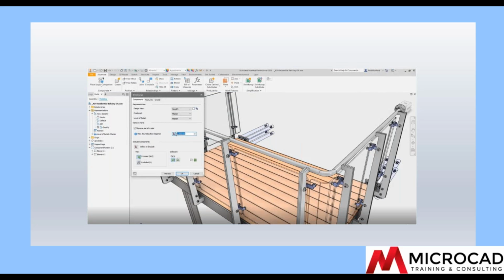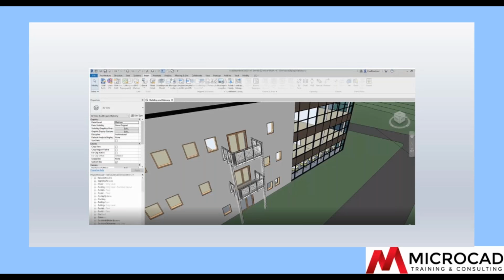Note that the manufacturer's model is much more detailed than the architect's. This is because the manufacturer has to have everything needed to make the product, while the architect only needs the parts for visualization. The manufacturer may make some further changes, maybe because of the engineering calculation or to reduce cost. The manufacturing model is simplified and passed back to Revit as a Revit family for the architect to review. This bidirectional flow of data could continue in design iterations until both partners are satisfied with the design.